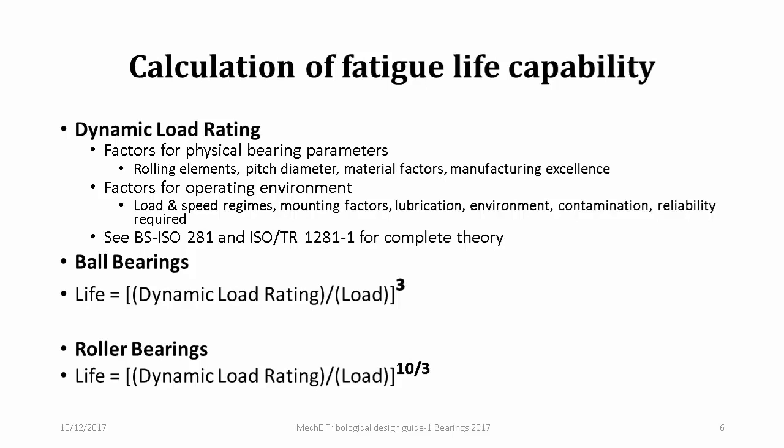There are then factors for operating environment, for load and speed regimes, mounting factors, lubrication, as you would expect, environment, contamination, and the reliability required. And the complete theory can be found in BS ISO 281, and there's also a supplementary technical report, ISO TR 1281-1, where you can find the complete latest form of these theories.